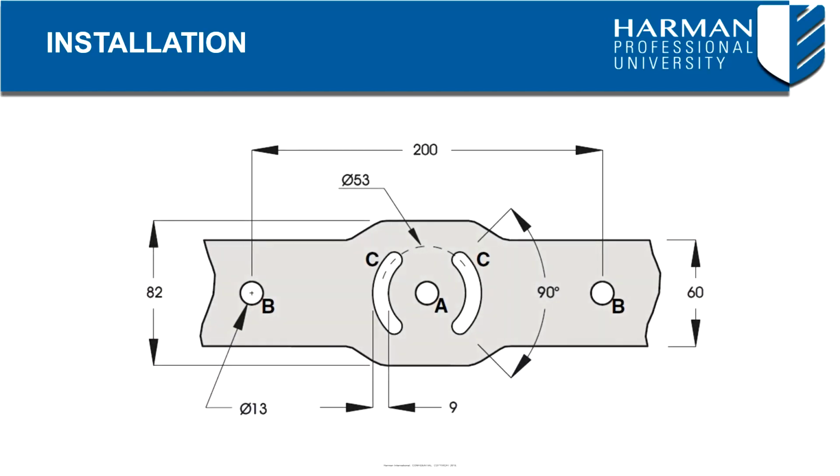It is also possible to install the fixture temporarily on a rigging truss or similar support. If you do this, fasten 2 approved rigging clamps to the mounting yoke with M12 bolts through holes B in the mounting yoke base. Be sure to suspend the fixture using the 2 clamps.